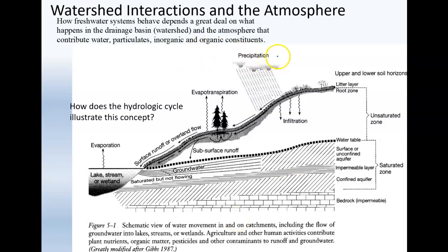And so most of the water that you see will get to a river or a lake or a pond by precipitation. And notice a lot of these process words end in the "tion." It could be rain, it could be fog, it could be snow, but when it melts, it will either infiltrate the soil and work its way into the groundwater, or it will run off as surface runoff or overland flow into a lake or stream.